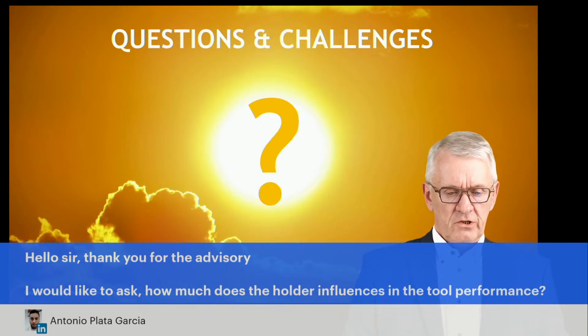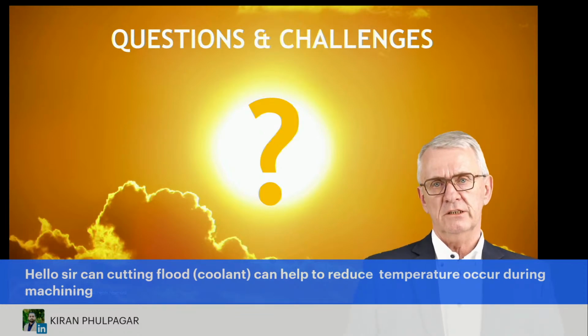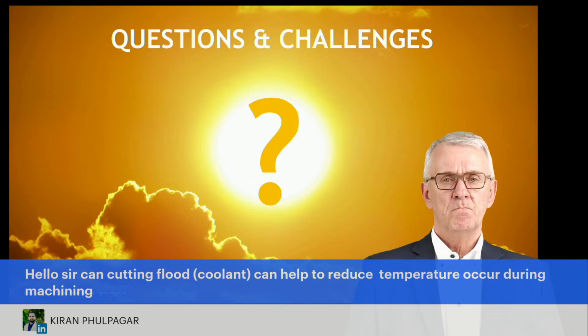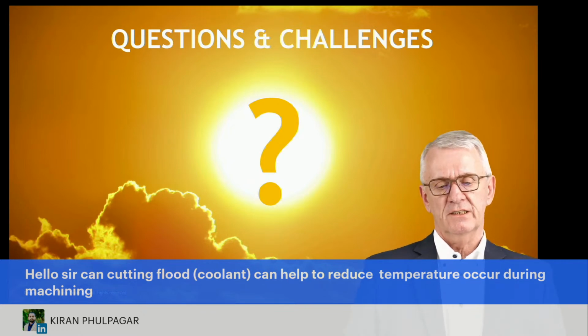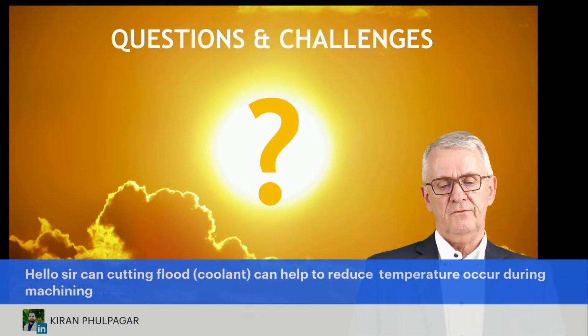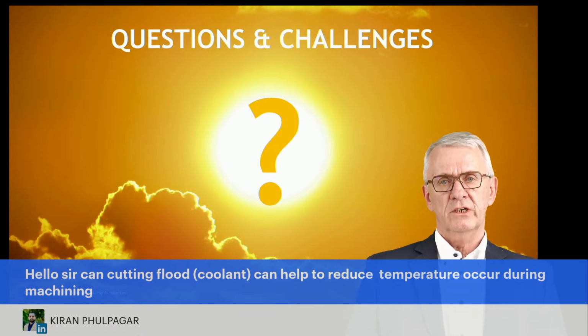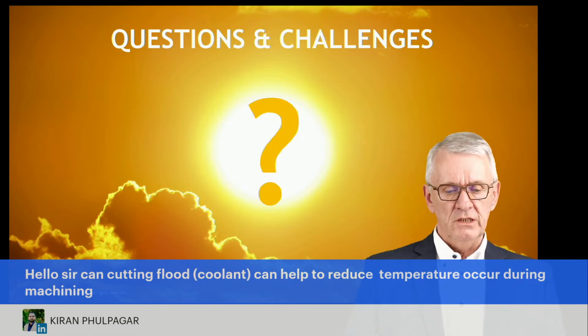The third question from Kiran: can cutting oil coolant help us to reduce the temperature during machining? Yes. To which extent is discussable, but it reduces the temperature. When it's well applied, remember what I said, when it's well applied, yes, it reduces the temperatures. Very clearly, and so far I just very briefly talked about the impact of cooling on cutting tools. Of course, cooling also is going to have an impact on your workpiece, the workpiece temperature, the surface roughness, the temperature of your machine tool, and so on.